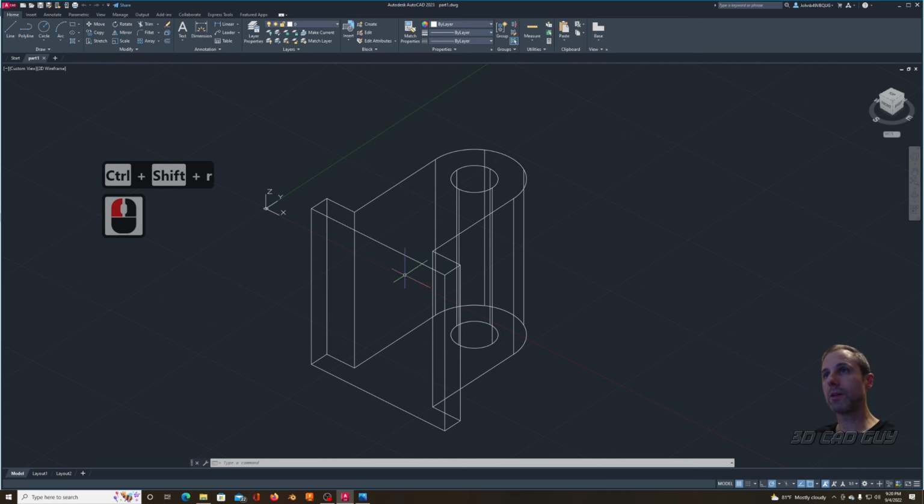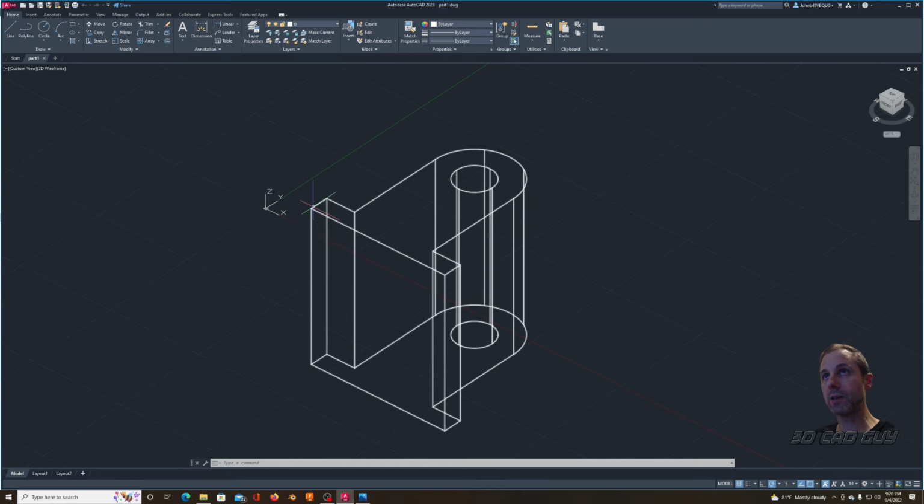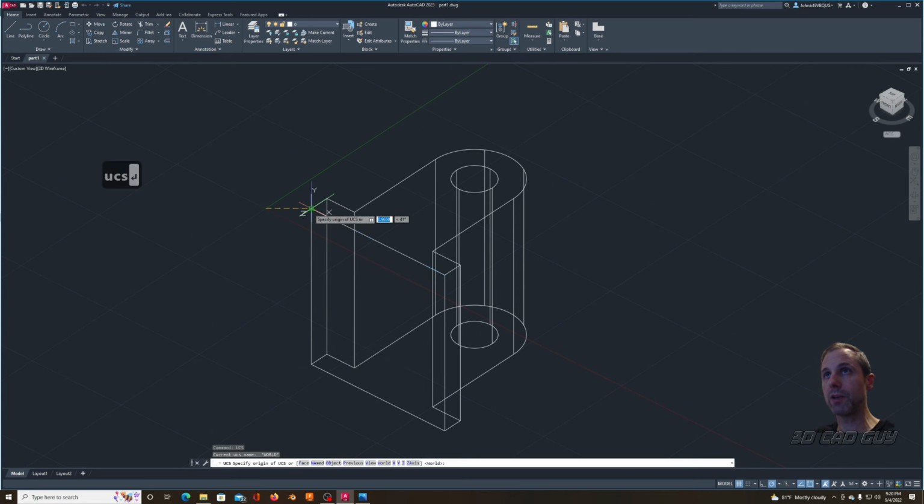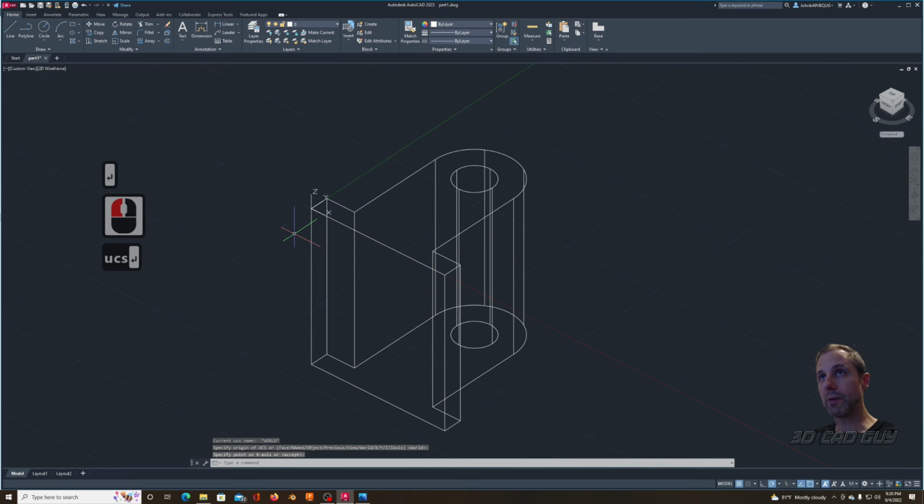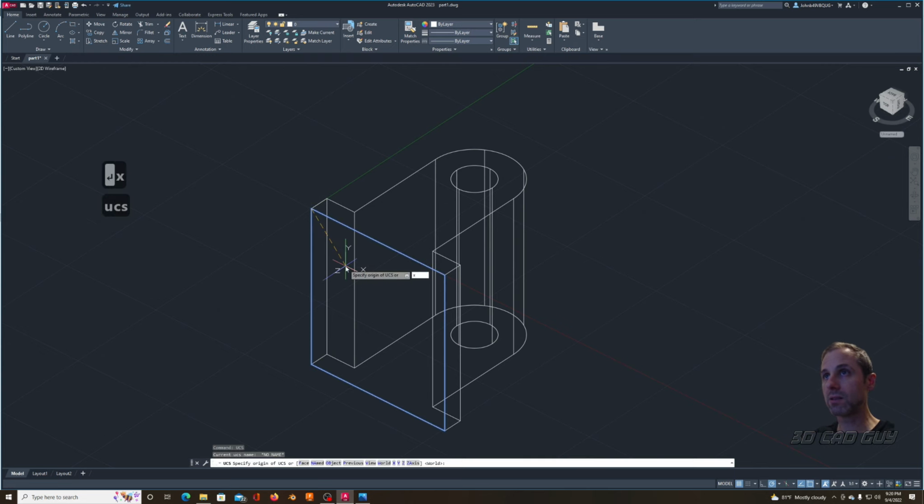All right, we're going to go ahead and put the bolt holes in for the mount. The first thing we've got to do is reorient this plane to this surface so we can put these holes in. Easiest way to do that, just move the UCS so you can put it in an area where you'll be able to really evaluate where you want to draw. So we've got to turn this plane to be aligned with this. So just type the UCS in with axis 90. I just rotated around this x-axis to rotate the plane along this surface.